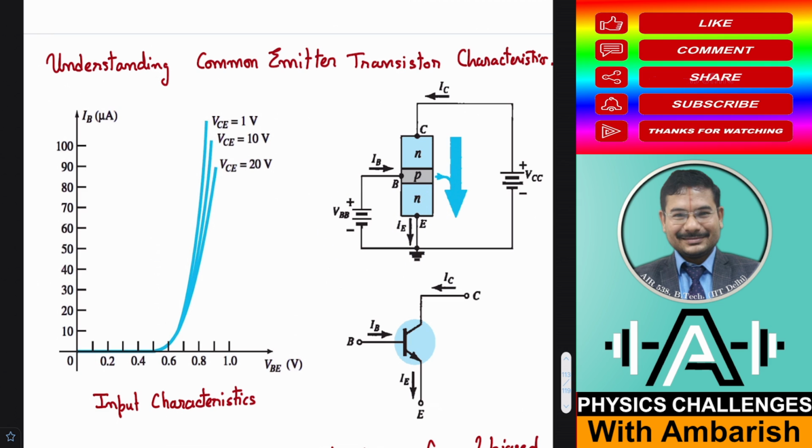Now what's happening? The base is very, very thin, unlike the diode. Here the base is a very thin layer, and it is very lightly doped. So whatever electrons are ejected into the base, most of them will cross over to the collector side. Why? Because the base is very thin, and the second thing is that the base has very light doping. So very few holes are available in the base, so electrons cannot combine with the holes in the base.